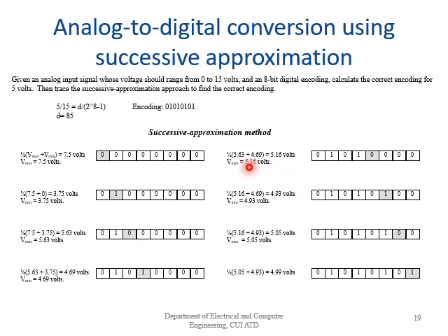Here we get 5.16, and again 5.16 is greater, so we are going to put 0, and we are going to replace the maximum with 5.16. Once you reach the last one, you can see that we have an encoding which is almost equal to 5 volts, and the encoding is 01010101. So this is how our successive approximation analog to digital converter works.